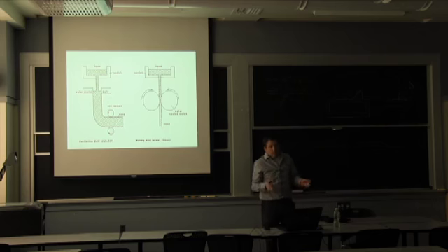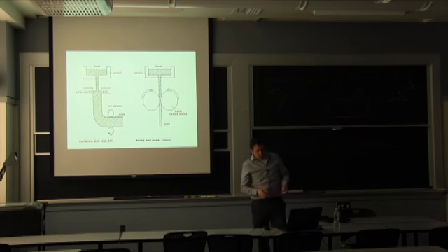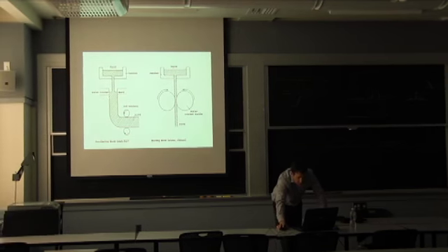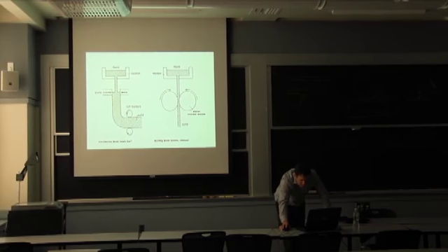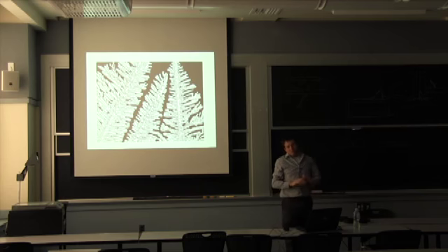I do want to point out that most of the time we're using steel as a wrought product. So you start with a liquid, you will form a big billet or a strip. So these are the two ways here. You have two rollers to solidify your liquid very quickly. This is a more traditional way of forming slab billets. What happens is you form dendrites. Not all the time, but in most cases you form some dendrites in this process.